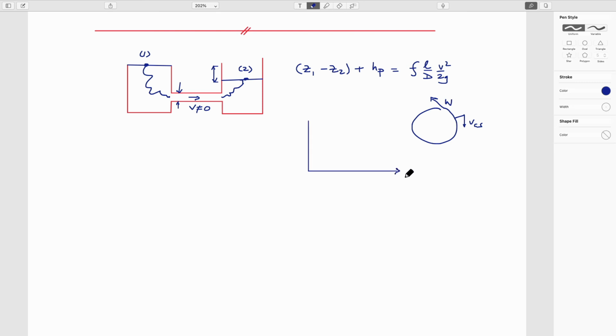And this diagram was velocity of the control surface and I guess the torque. Torque would be going in this direction, right? T equals force times radius. Then we said that the two conditions that we applied: one is that you hold it static, so it's going at 0 velocity, and the torque on that is a maximum. And if you have it going around at the maximum velocity, then by letting it go, the torque is 0 and the velocity is a maximum.